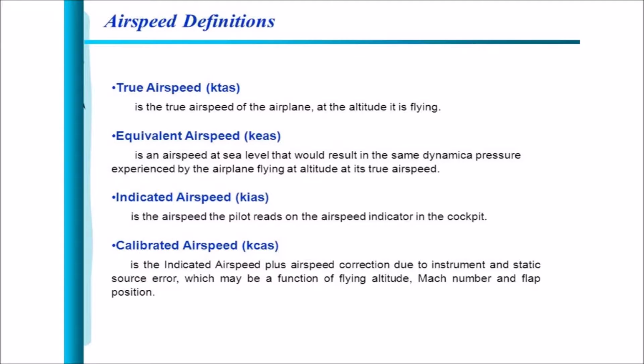Abbreviations are very commonly used when referring to airspeed of the aircraft. The knots calibrated airspeed, abbreviated as KCAS, is indicated airspeed corrected for position and instrument error and expressed in knots. Knots calibrated airspeed is equal to knots true airspeed in standard atmosphere at sea level.